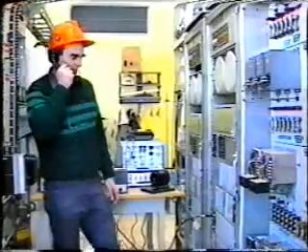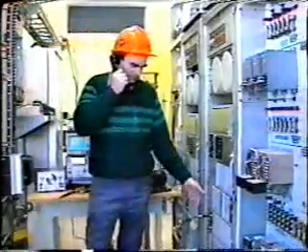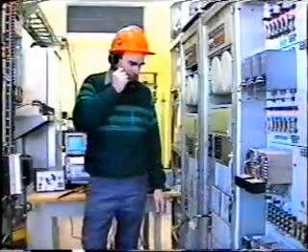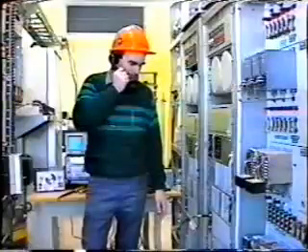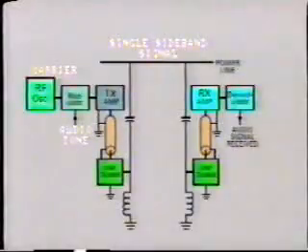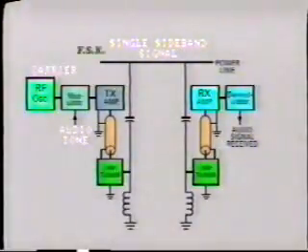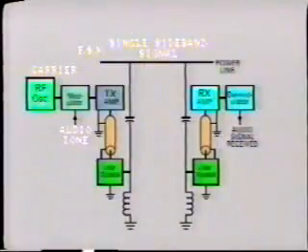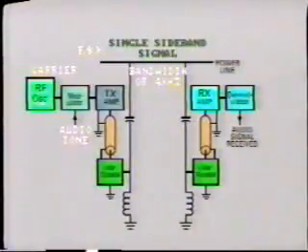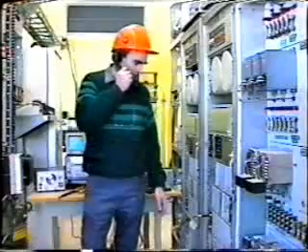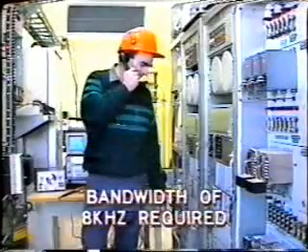You'll find many power line carrier installations using single sideband or SSB transmission, providing audio communications in addition to protective relaying. For protective relaying, audio tones are superimposed on the carrier signal to provide FSK signaling. Usually, the SSB carrier operates within a bandwidth of 4 kilohertz to accommodate all of the various audio signals. For the usual two-way communication, a total bandwidth of 8 kilohertz is required.